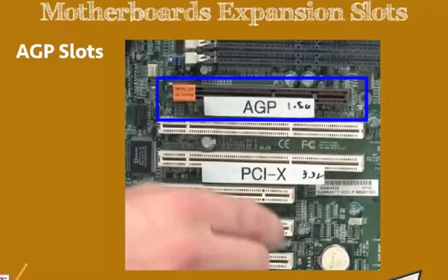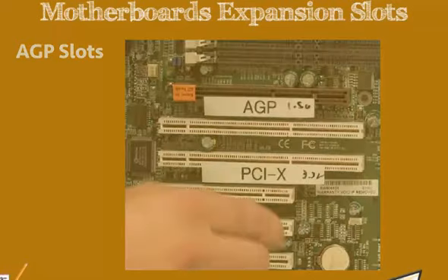A smaller card will still fit into the slot, but the sticker keeps us from offsetting it incorrectly and misaligning the pins. However, if we do have an AGP Pro card, we can remove this sticker so that we can place the card in. But if we aren't using the AGP Pro slot, then we should replace the sticker and put a little bit of tape over that to prevent us from misaligning pins.